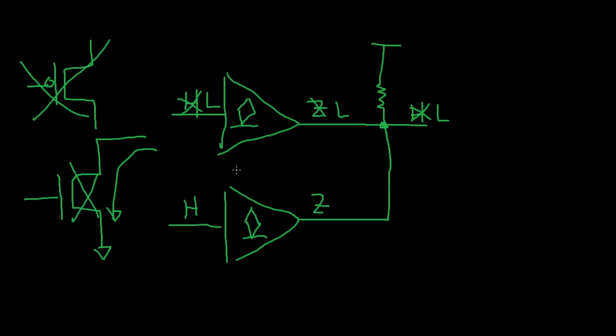So what happens whenever you excessively load an output? And what do I mean by excessive loading on an output? If we take a standard CMOS output and connect it to a capacitor, we would usually call this a normal load, as long as it's within the datasheet specifications. Whenever you go to the timing and switching characteristics of a device, you're going to find that most of them are rated to 30 or 50 picofarads. Not very much capacitance. But with a 50 picofarad load, the device will continue to act normally.